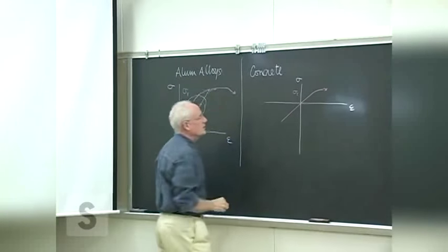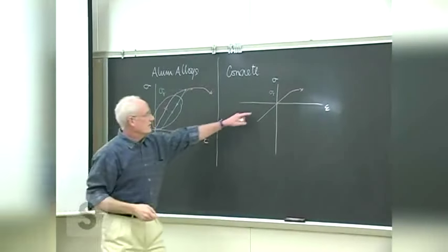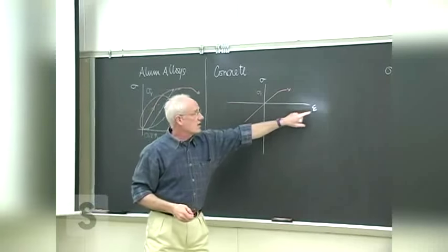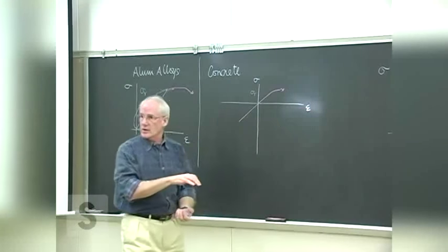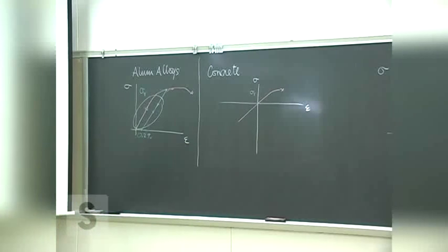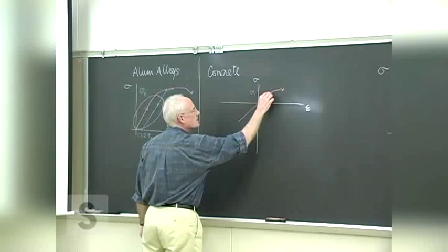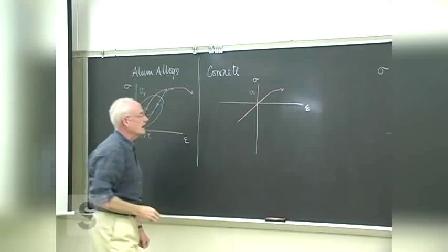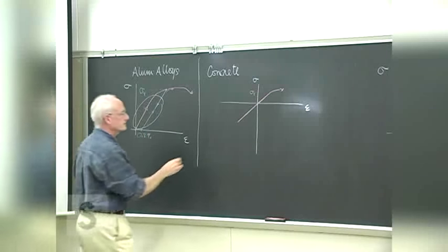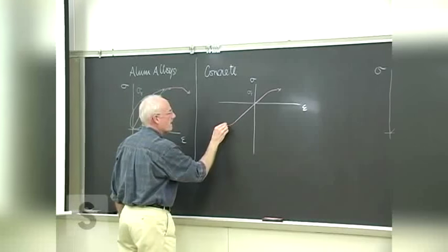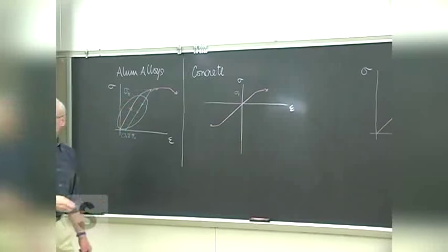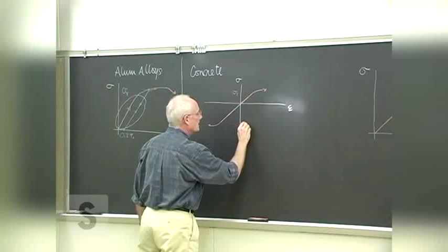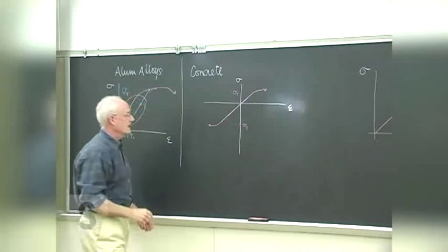test, which would look like that because we take compressive forces to be negative, but it's also a shortening of the material itself, so it would have a negative strain as well. These slopes are constant either side of the unloaded condition, but the concrete goes much farther in compression than it does in tension.